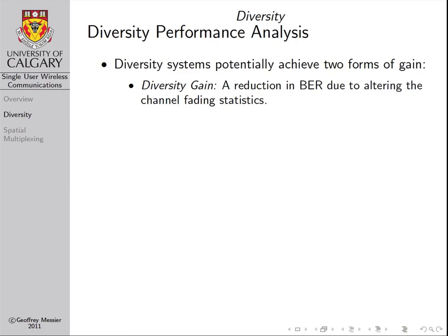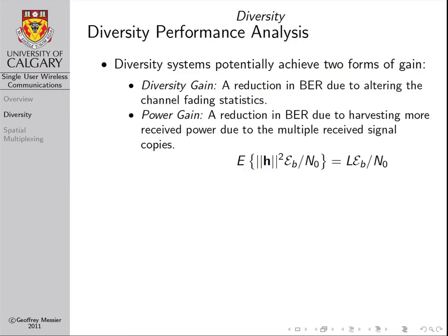And it's important to note that in those slides I kept the distributions normalized so they all had the same mean. So there wasn't necessarily a gain in average received power. It was basically just a bit error rate gain due to changing the shape of the distribution, spending less time close to 0 and more time concentrated about the mean.